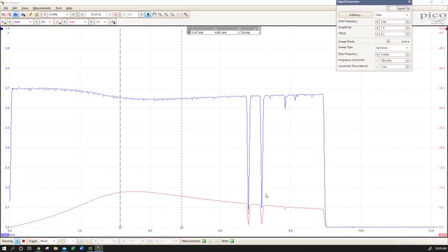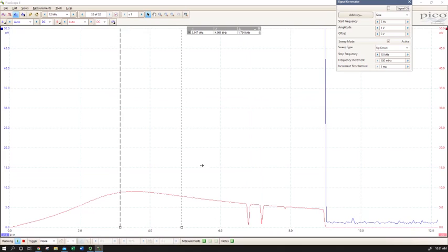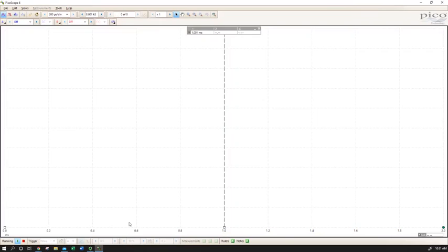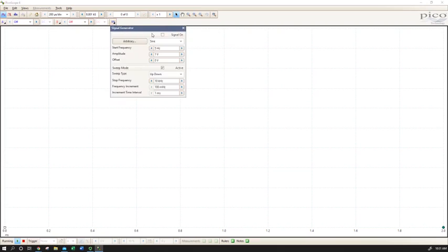So I can stop this, and I know where to start looking when I do my scope display, where I'm going to look for the lack of a phase shift between my full circuit voltage drop and my resistor voltage drop. So I'm not applying a signal anymore, and I'm going to switch over to my scope mode. So again, 3 kilohertz to 5 kilohertz. We think we're going to find resonance somewhere in there. So this ends up being a bit of a resonance hunt. So let's start with 3. So 3000, and we're going to turn it on.